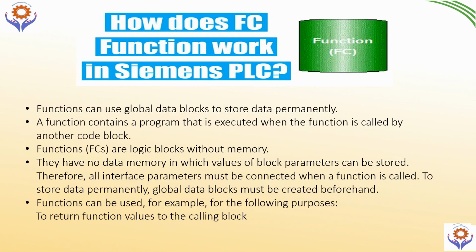Now we will look at what a function is. Functions can be used like global data blocks to store data permanently. A function contains another program that is executed when the function is called by another program code block. That is, functions can be called from the main OB or from another block.